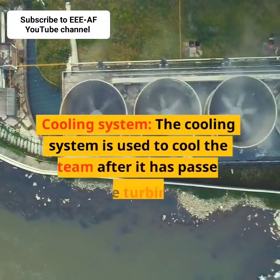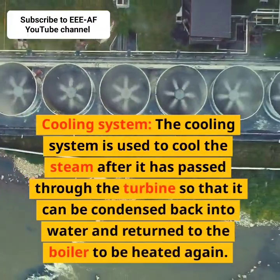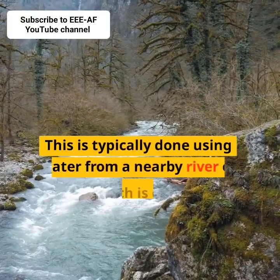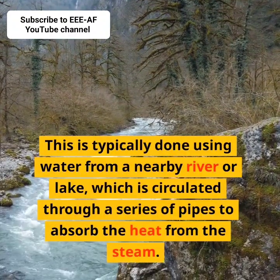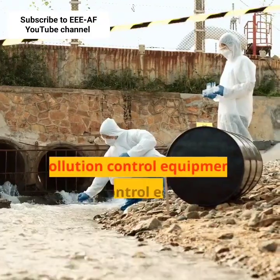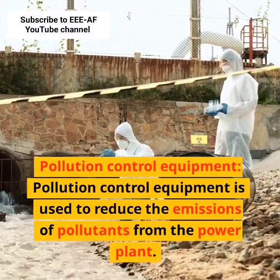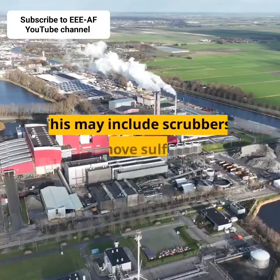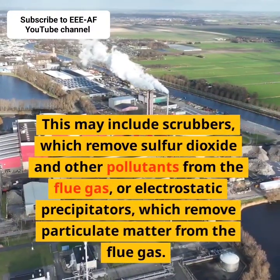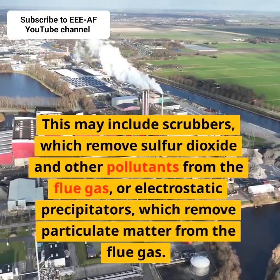Cooling system. The cooling system is used to cool the steam after it has passed through the turbine so that it can be condensed back into water and returned to the boiler to be heated again. This is typically done using water from a nearby river or lake, which is circulated through a series of pipes to absorb the heat from the steam. Pollution control equipment. Pollution control equipment is used to reduce the emissions of pollutants from the power plant. This may include scrubbers, which remove sulfur dioxide and other pollutants from the flue gas, or electrostatic precipitators, which remove particulate matter from the flue gas.